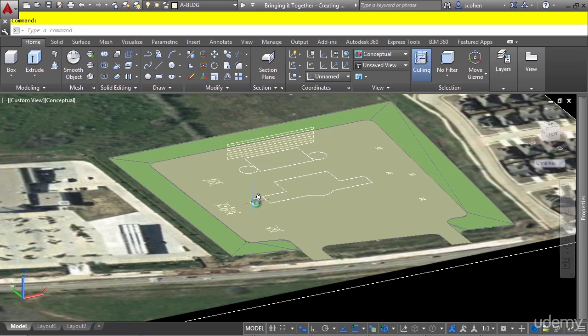Before we begin, let's check our settings. First, let's check the DELOBJ variable, and normally when you have it set to 0, it retains that 2D geometry, which is a good idea sometimes. In this case, we want to get rid of the 2D geometry as we create the 3D solids from them. So let's enter a value of 1, which will remove all the geometry.